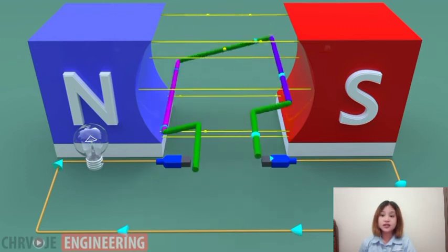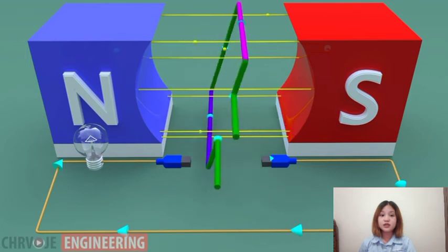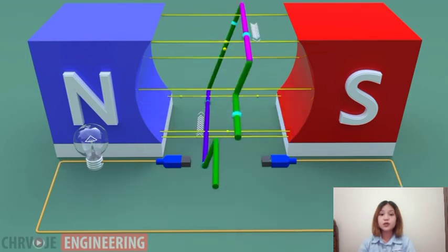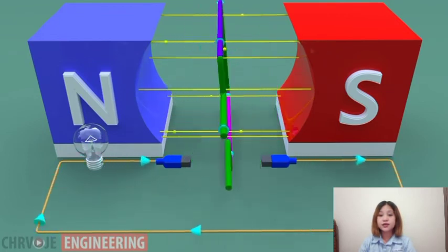And again, when the coil comes to this left position, again the direction of the current changes. So the brush will have to contact the left wire. And again, if we want to keep the current direction the same, we must change contacts with every rotation.